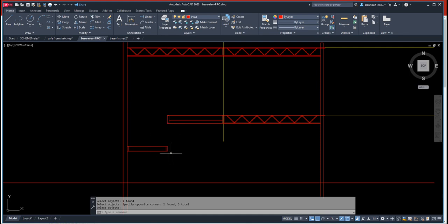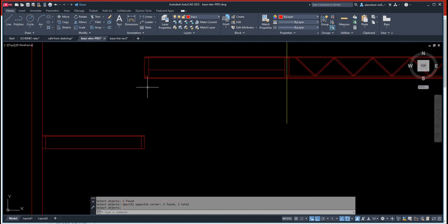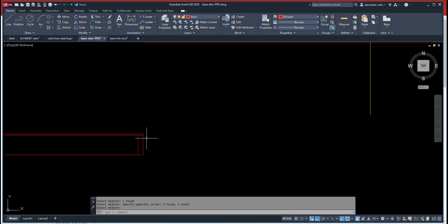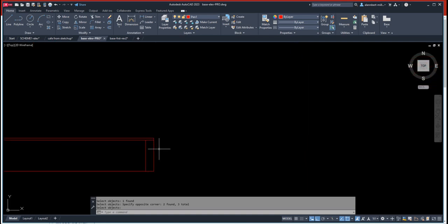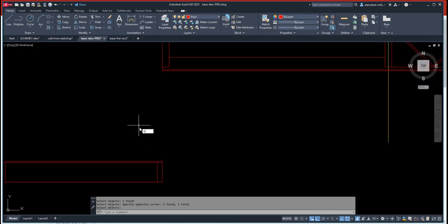Okay, and you're going up and the landing, and you don't see anything, but that is certainly the landing. Okay, so in this case, how do you prevent people from falling? Well, you may want to put a glass here. Okay, so if that's part of your design, that's part of your design. That means that you want to probably build something here, or just put a railing. It doesn't matter. So if you want to put a railing, railings are 36 to 42 inches.